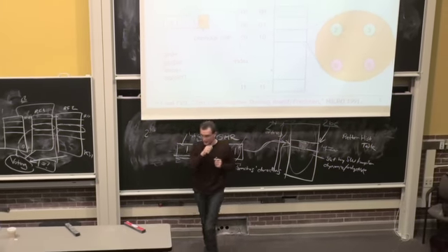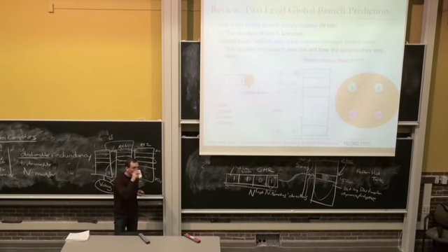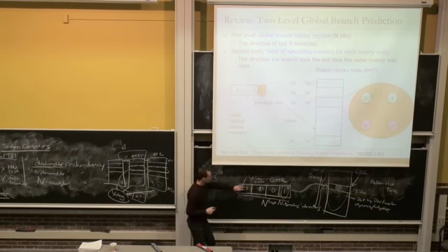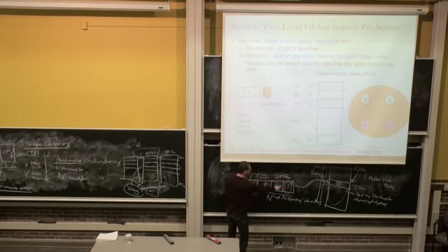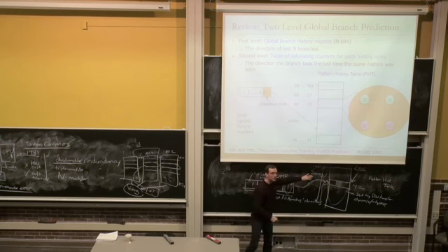Yes? So I'm a little confused. Does this have entries for all branches of a particular program, or one history for one branch? There is no branch here, right? These are the, where did your last n branches go? Taken, taken, not taken, taken. So just history for the whole program? Yeah, history for the whole program. That's the simplest global predictor.